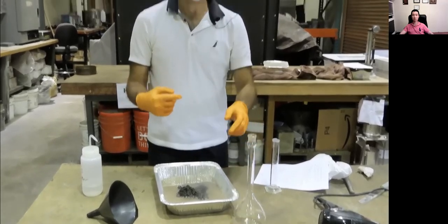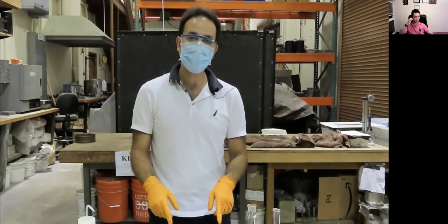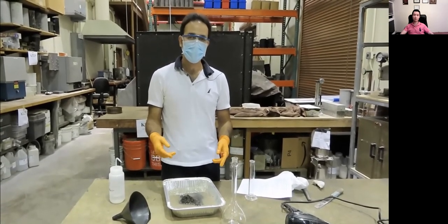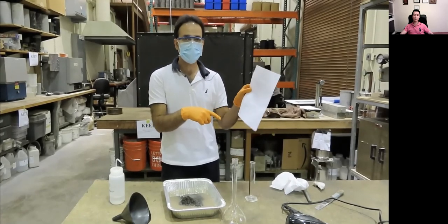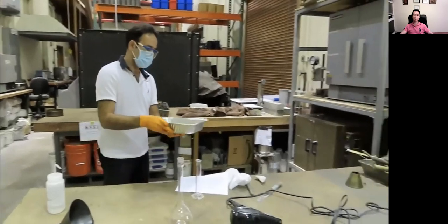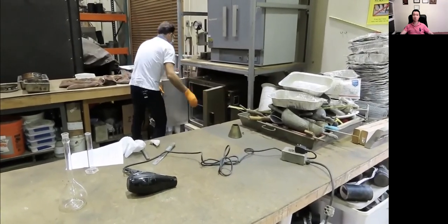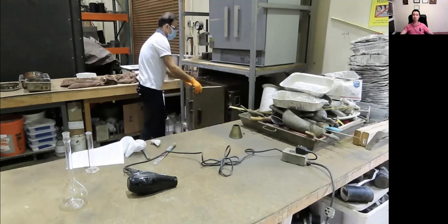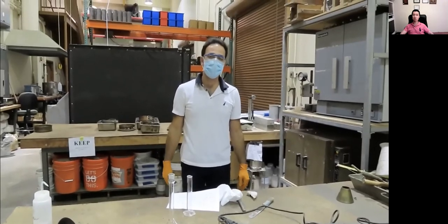And like my coarse aggregate, I have to put the container in the oven, wait for 24 hours to get the sample in oven dry condition, and then compare them for the absorption capacity number, and then use the formulas that you have in your textbook or in the instruction to get the specific gravity of it. So I just need to put it in the oven, and then get back to my sample tomorrow to weigh them and report the numbers to you guys.